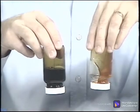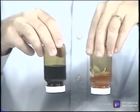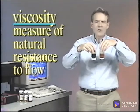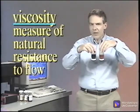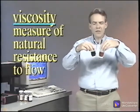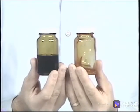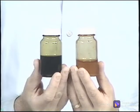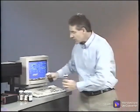Viscosity is the measure of a fluid's natural resistance to flow. Oils flow more freely at higher temperatures and are resistant to flowing at lower temperatures. So the measurement must take into consideration the fluid temperature when measured. Viscosity is measured in centistokes at the temperature in degrees centigrade. There are tables for the viscosity of each oil at 40 degrees centigrade or 104 degrees Fahrenheit and 100 degrees centigrade, which is 212 degrees Fahrenheit, or the boiling point of water.